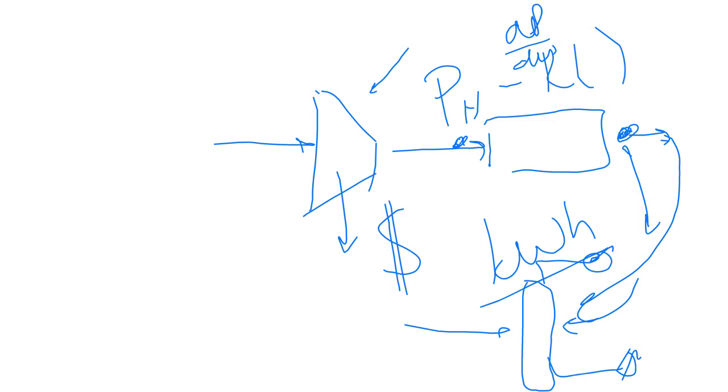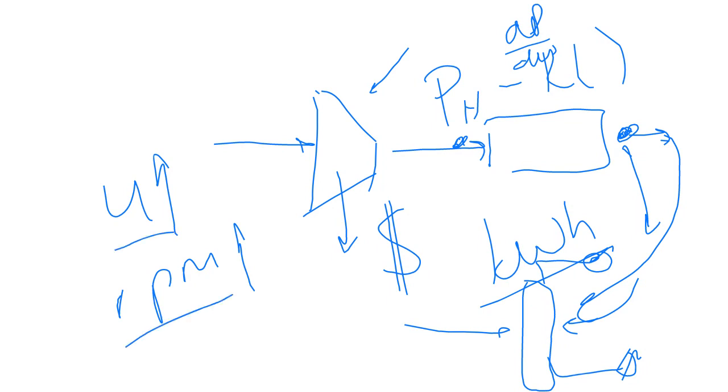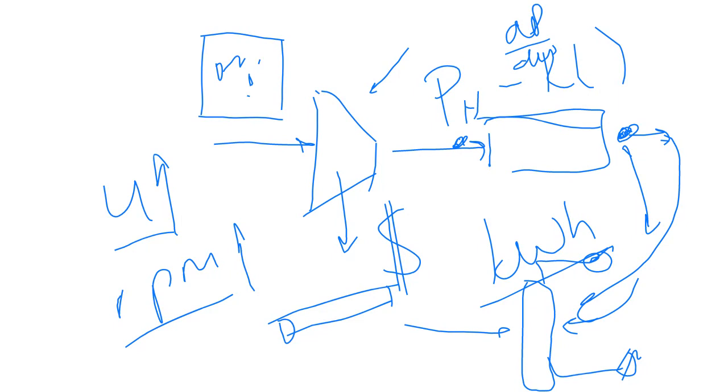So if I say I want to exclude external diffusion, I want to have high enough linear velocities, high enough flow rates in order to make sure that I do not have external diffusion effects. Generally, in my experience, in packed bed reactors, where I have a tubular reactor, so not just one big reactor that is adiabatic, it is quite easy to eliminate.